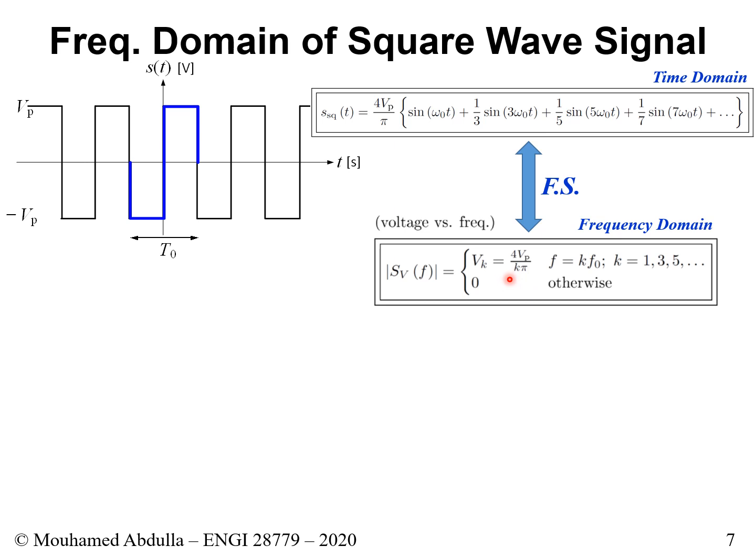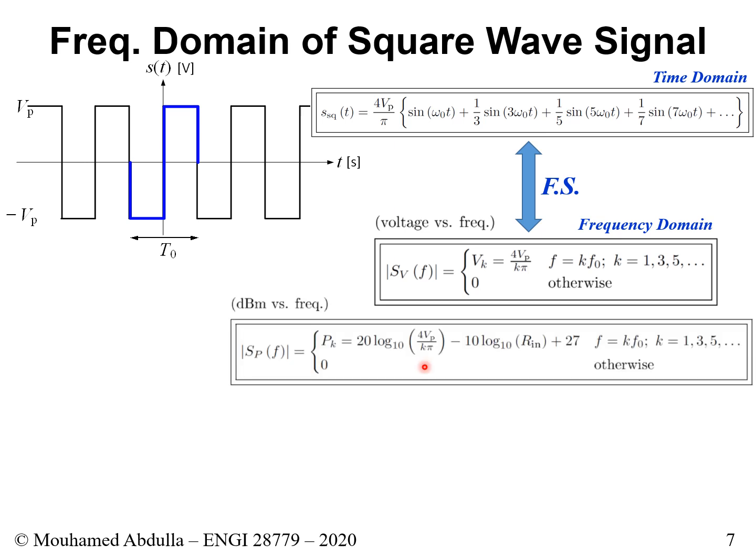I hope that's clear. We've seen this in lecture 3 and earlier in this lecture. So we could do that, or if you want, you could use the fast track approach, which is essentially the formula that we derived in lecture 3 and also used earlier in this lecture, where we do 20 log 10 of Vpeak, whatever Vpeak is. In this case, Vpeak is not this Vp, it's this entire thing, right? So you want to find the Vpeak of each sinusoid, which is this entire thing.